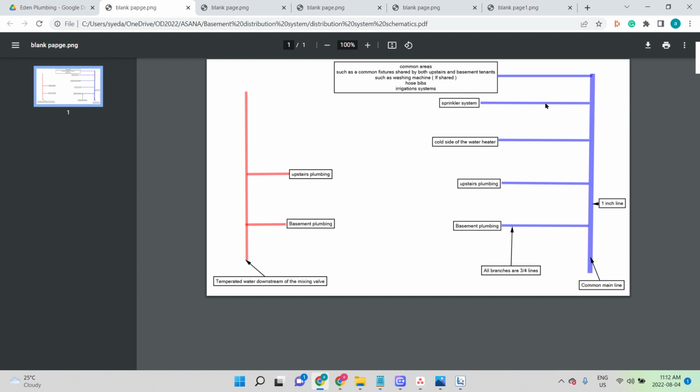It can come from here, but there is a process. If I connect it like this, leave it here and cap it off here, now this water gets stagnant because there's no activity going on downstream of it. So this water will be all dirty. This is really long. It's not going to be accepted because when the sprinkler does activate, all the dirty water is going to come out and hit somebody. So the inspectors don't like it.